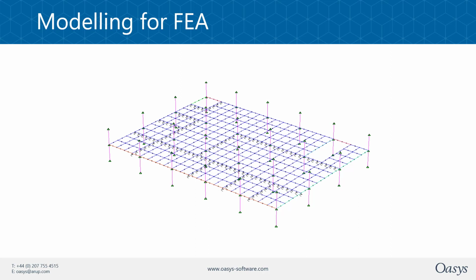Loading, you've got to include the minimum credible dead load and the design guide's recommended live loads, because these loads are then converted into mass, and mass resists accelerations. So a low mass is actually more conservative, which is the other way around to the normal static analysis.